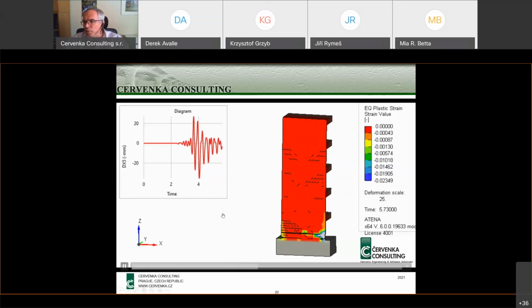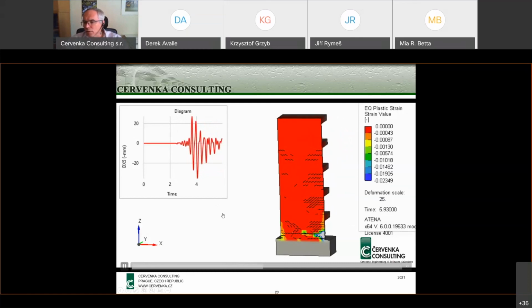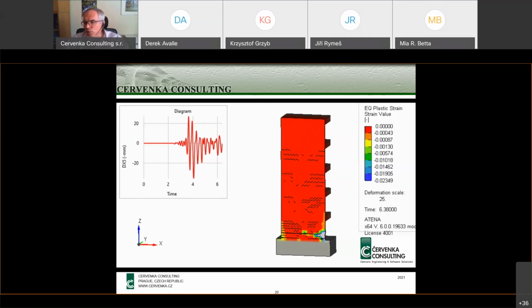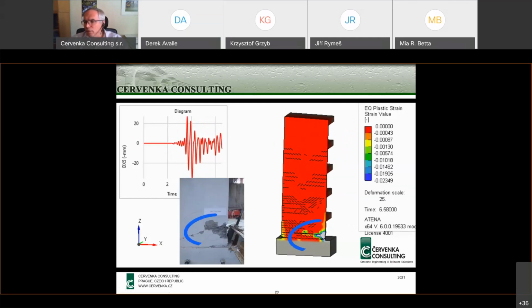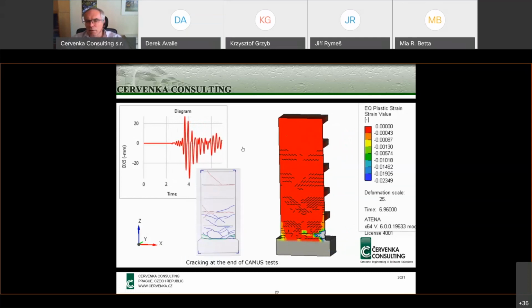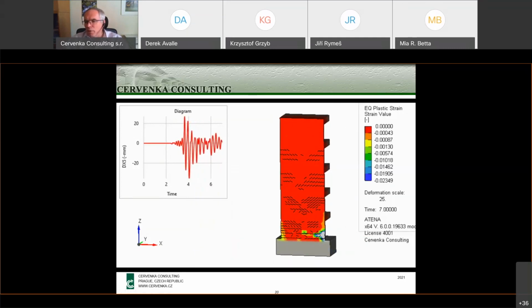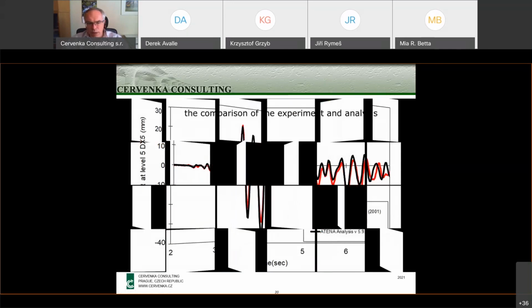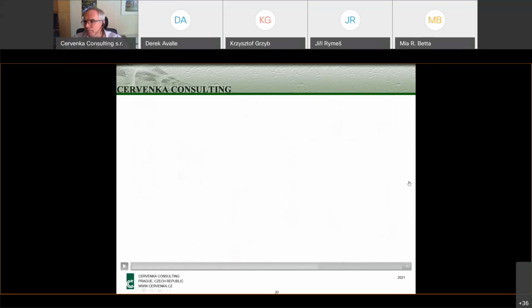Also in this 18-story building, the slab was elastic, because we were not so interested in that. But there is no problem really to activate also nonlinear elements. Of course, this may make the analysis more demanding. The problem then will be that the slabs may start failing, so you may have problems reaching convergence and so on.